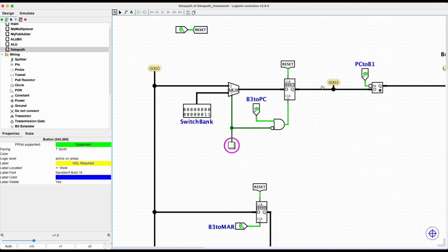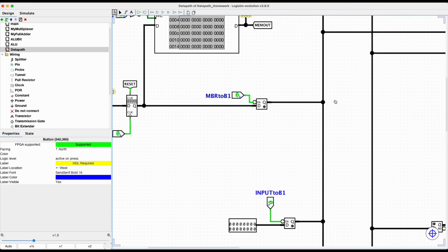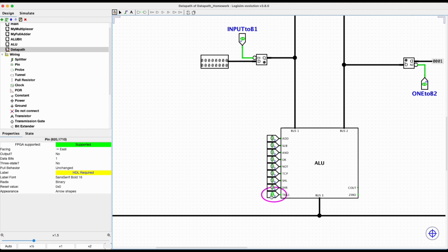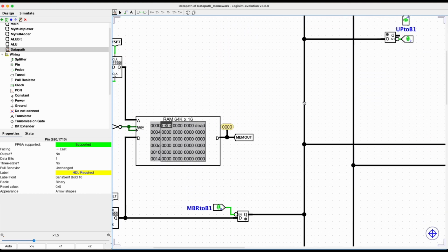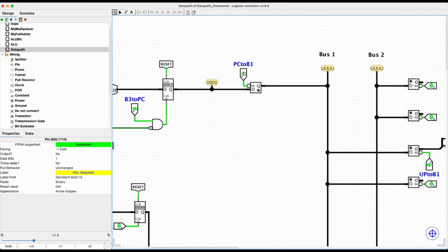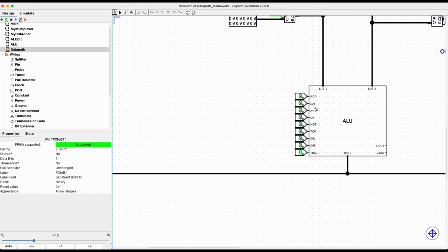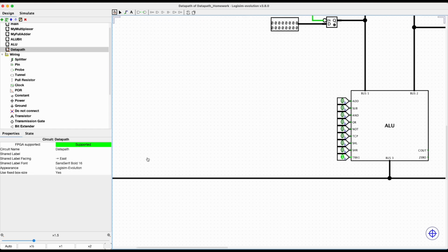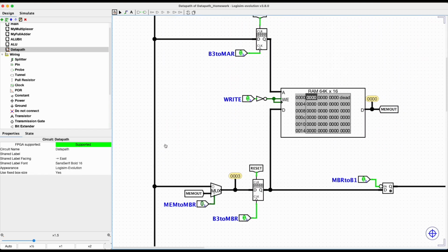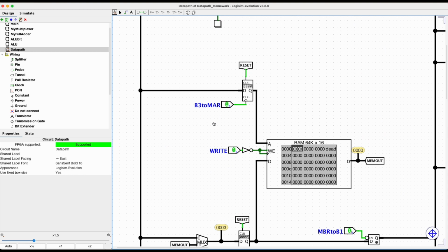And you see we got 3 into our program counter. Since we got 3 into our program counter, we go down here, we turn on TRA1 right here, and then turn on PC to bus 1 too, so we could get the 3 onto our bus 1. And then TRA1 passes that 3 through there, and we're going to clock it into our memory address register right here. So bam, now it has 3.